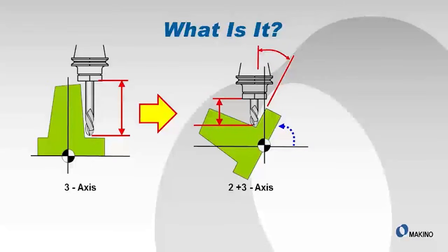Maybe 10 years or so ago started the advent of tilt and rotary tables. And what we could do then was position the 2 most inaccurate or the slowest of those axes. That's what the first 2 are. So your tilt and rotary you would position, and then you would machine the part using the X, Y, and Z, cutting the part in basically 3 axes.